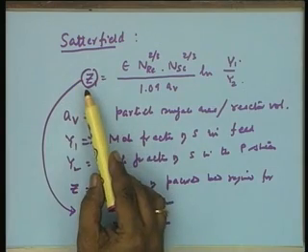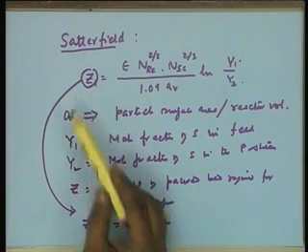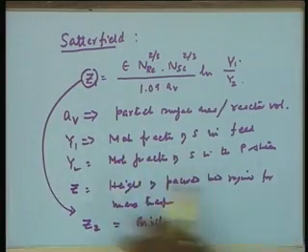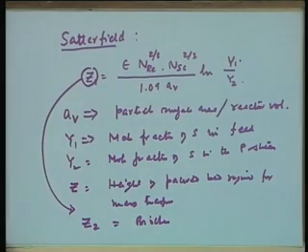On the other hand, if this height required is reasonably high, then you forget about biochemical reaction and design the reactor based on diffusional requirements, based on the mass transfer coefficient. The length of that reactor will be equal to this. This is the height of the reactor. Of course, this is basically an empirical equation, but depending upon the reactor operation data, it gives the height required for effecting the mass transfer across the film.